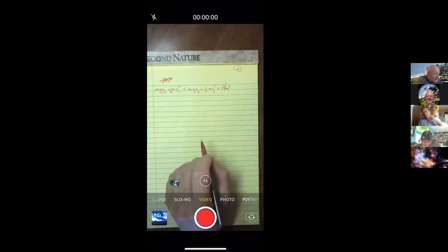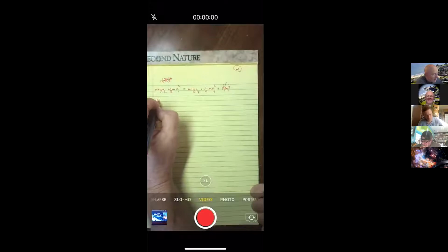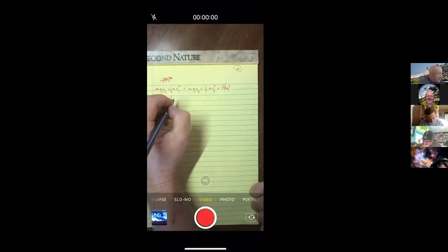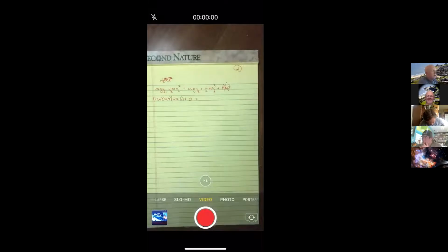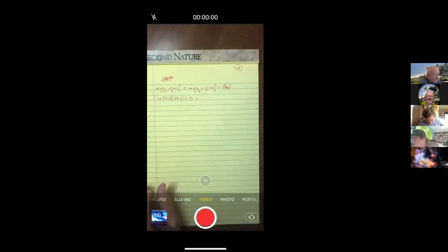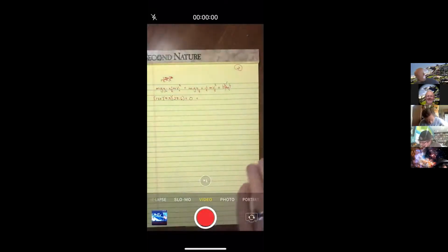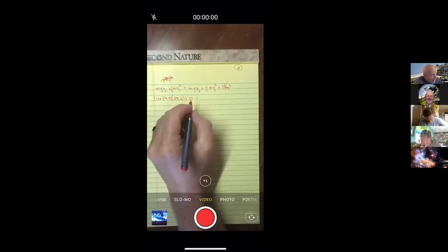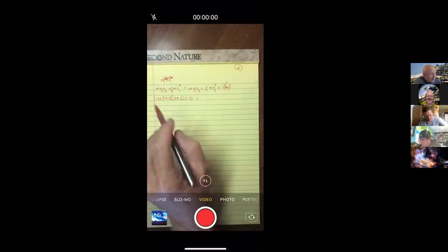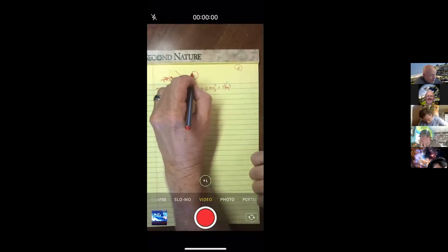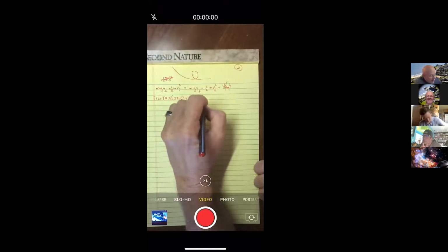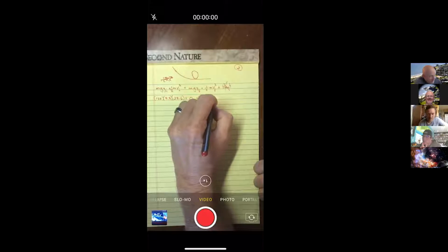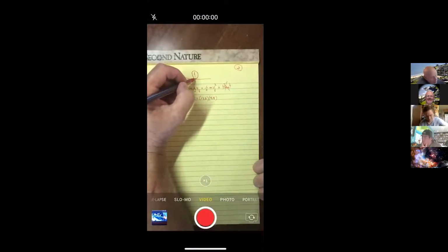Okay, so if we now put in the numbers that we know for this problem, we've got the mass at 120, g is 9.8. The vertical height it starts with, I wrote down as 23.6. And maybe just to make it look complete, I'm going to put down a 0 for the initial speed. So that's an important first step. Then it goes down to the bottom and around the loop. That's the mental picture I have in my head here. And now it has a height that is the diameter of this loop.